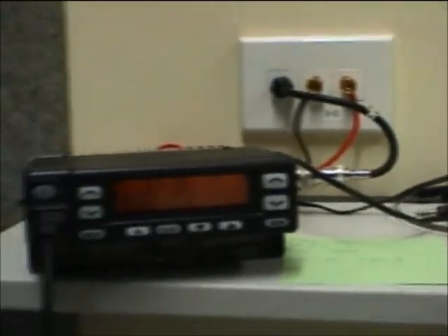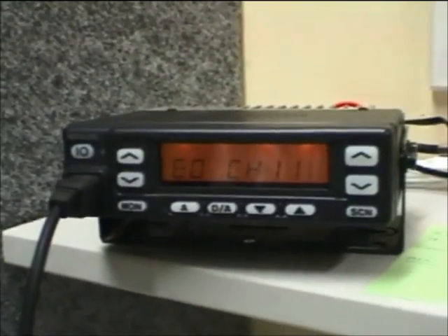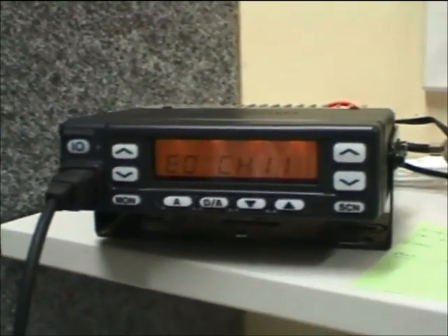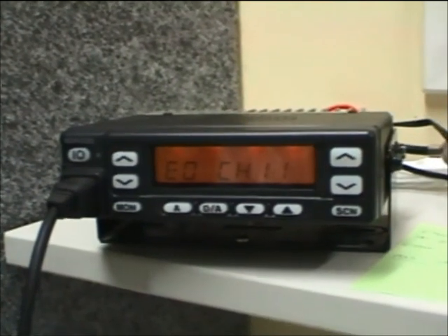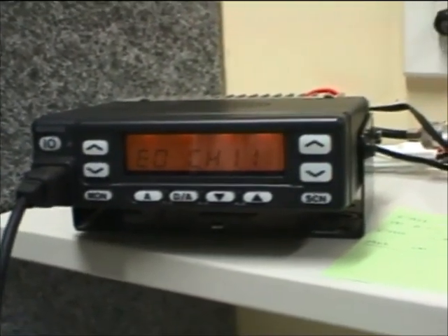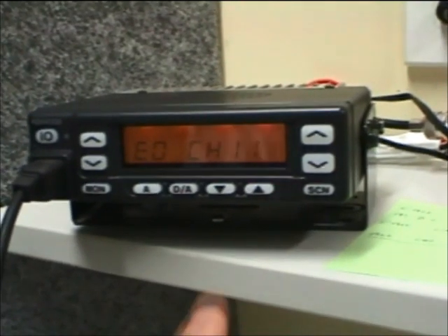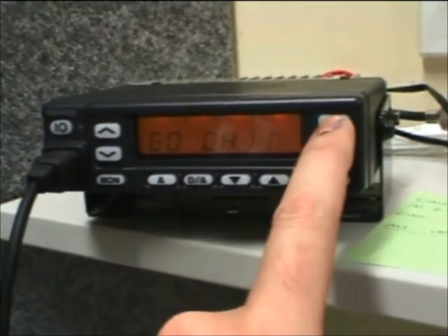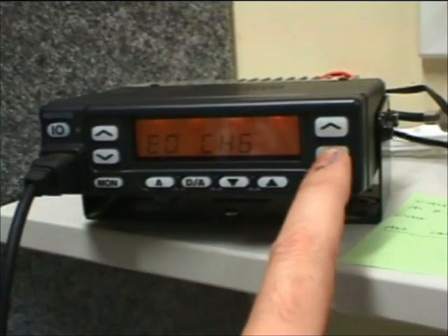Now I just want to show you a set over here. This is a commercial FM VHF set, and what they've done here is they're not displaying any frequency information. Remember I said we've got a microprocessor controlling the local oscillator. You can actually put labels on the channels that suit you. So this is the Emergency Operations Centre channel 11, channel 12 and so on. You can see the channel numbers.